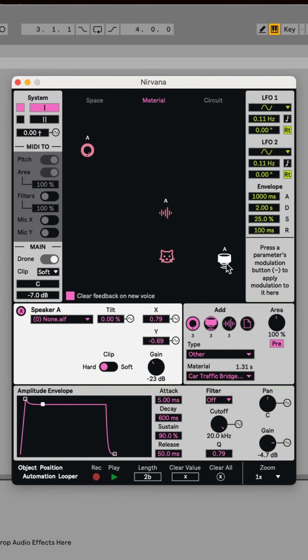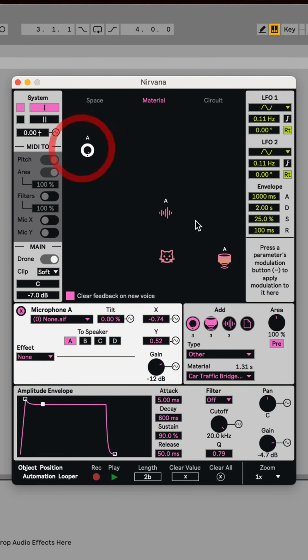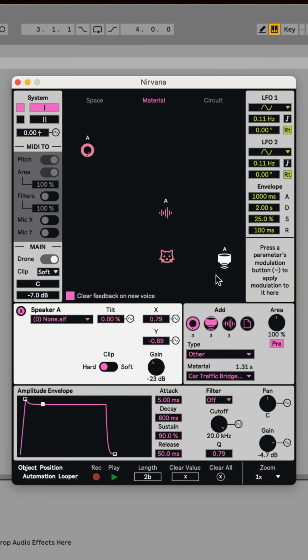It more shifts. What I'm doing underneath is actually way more complicated. I'm detecting the modal peaks of the material IR, and then you essentially shift those up through FFT filtering of sorts, depending on the tilt amount. So this is a cool thing to modulate and get some pretty wild sounds out of. You can also tilt both the mic and speaker. Keep in mind you might get some gain loss from doing that, so you might have to boost the gains higher if you're doing tilting. It just all depends.